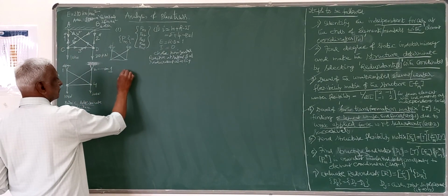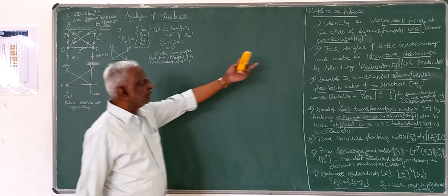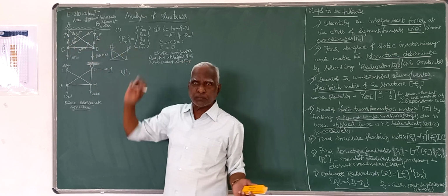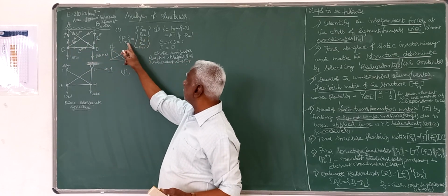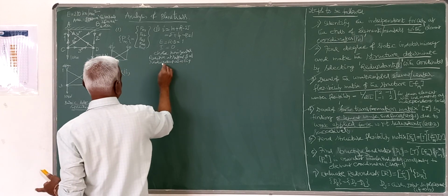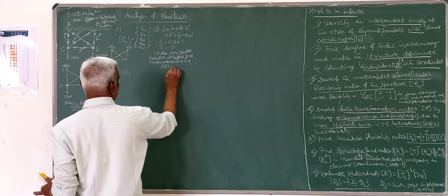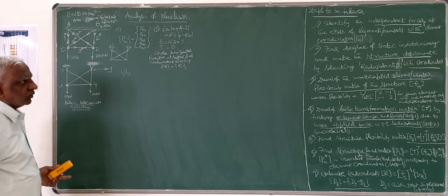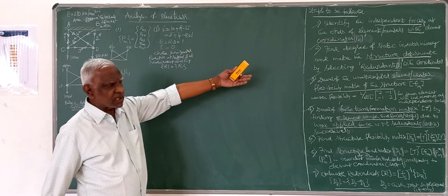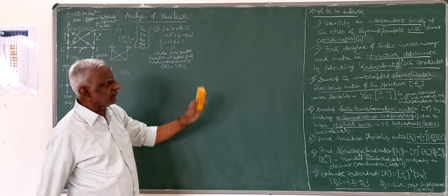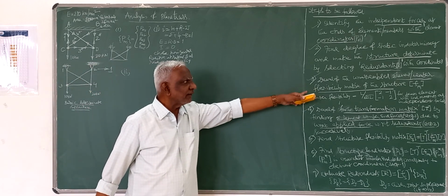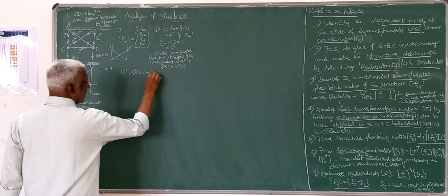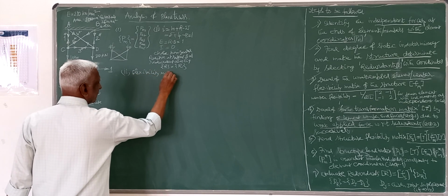Then third step. Here I have indicated first step, the element coordinates, that is member forces to be determined, that is PM, PM1, PM2, PM3, PM4, PM5 and all, and there is only one redundant, that is R1, corresponding to this global coordinate. So those are the first two steps which we have to follow, and that I have completed. Next, we have to develop the flexibility matrix, unassembled flexibility matrix. That is the third step.